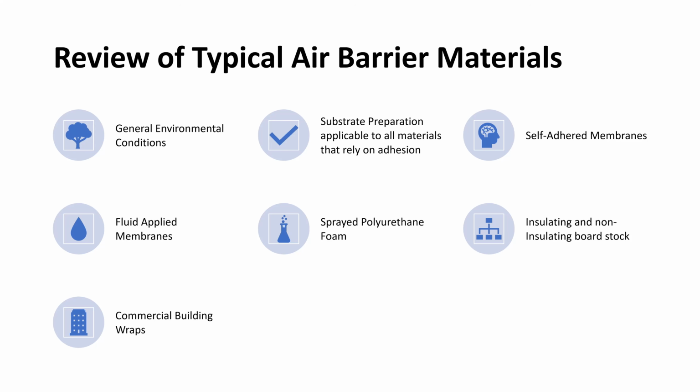So in essence, we're using an insulation board, taping seams, or we're using something like exterior gypsum, plywood, whatever it happens to be, and we're taping the joints and seams. And then the last being commercial building wrap. So that's like the house wraps that you might see on a house, single family, multifamily, or large commercial buildings too. So we're going to dig into these.